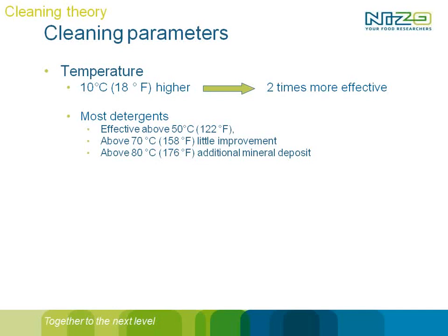degrees C in your CIP tank, because then you know that at least a temperature above 70 degrees C will be reached during cleaning, which is more or less the rule of thumb for the cleaning process. If you go below that, we see that the effectiveness is too low.